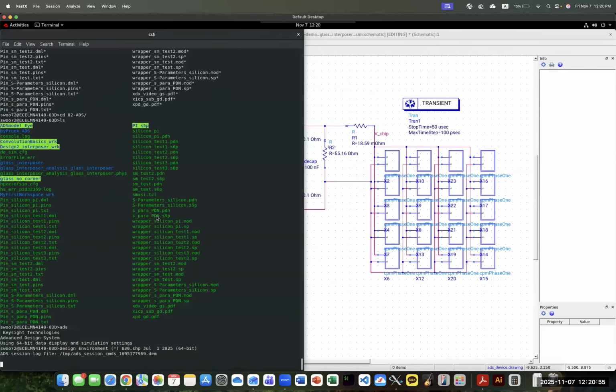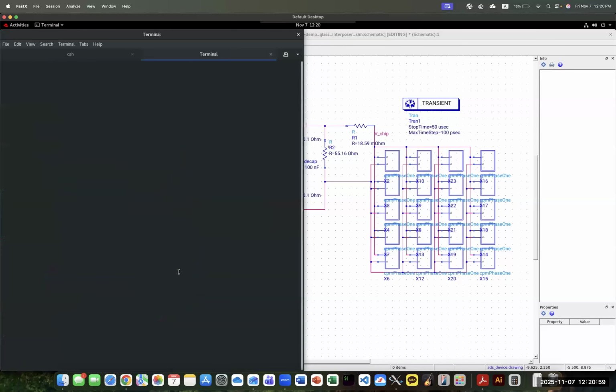It's PWL, but it's basically from one simulation run with one set of activity factors. The second set of activity factors is going to be a different CPM. So we're going to have to play a little with that setup and see how we can organize it, and what would be a reasonable assumption for changes in activity factors.